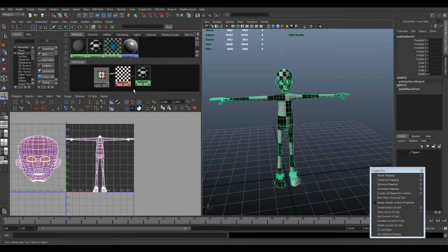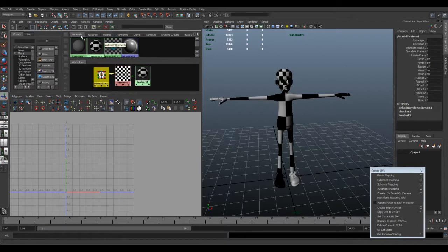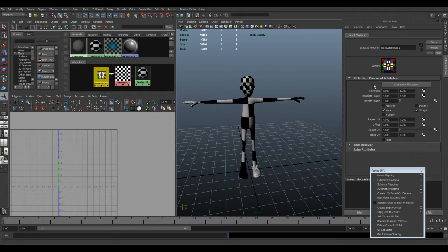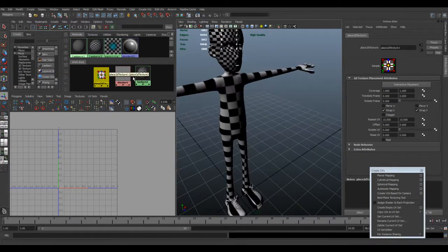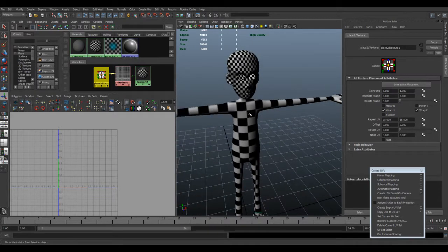checker textures. So what I'm also going to do is come into my material editor, into my working area down here. I'm just going to open the attribute editor by pressing Ctrl A. I also want to see this repeat UVs. Now, I want to make them a similar size on both, but first of all, I'm going to make this 15 by 15, like so. Obviously that doesn't change the mapping, it only changes the actual texture that you're applying to it. So basically I've made those square textures smaller and higher res, but I want to be working with a reasonable amount.